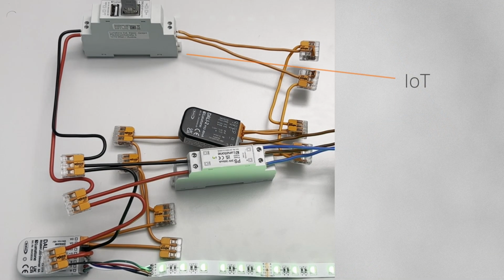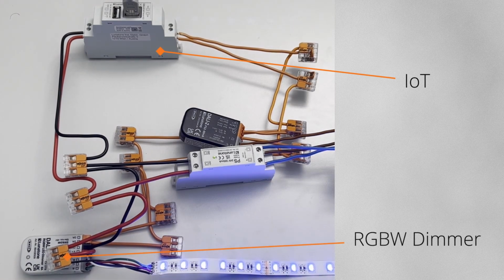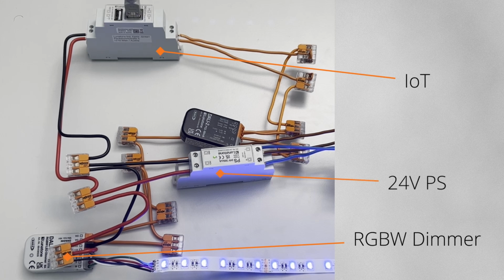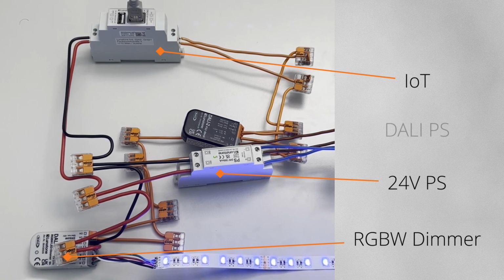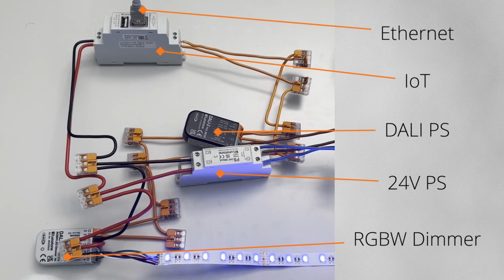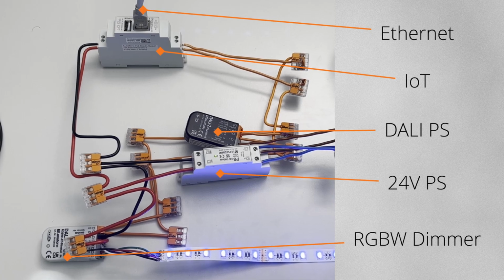In this test setup, we'll be using an IoT Node Red interface connected to a LED RGBW dimmer. We will need a 24-volt power supply for the dimmer and the IoT device, as well as a DALI power supply for the DALI bus. Finally, we will need an Ethernet cable to connect the IoT interface to our computer or network.